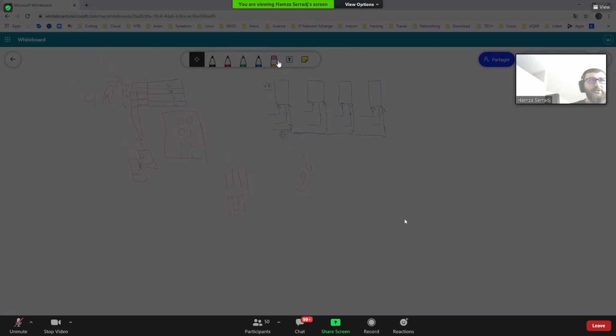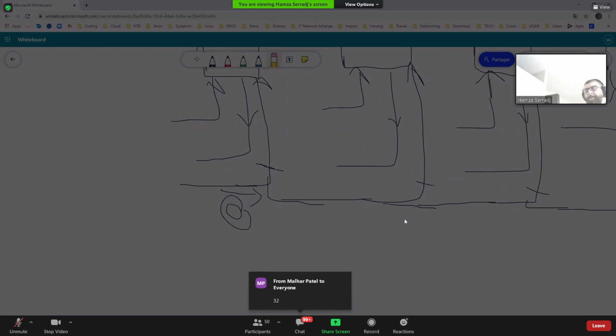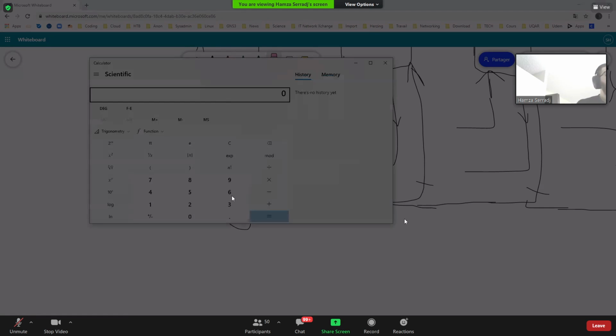I have 1024. With how many wires can I address this 1024? So what's gonna be the width of my address bus here? By 32? Well, let's take the calculator, right? What is the possibility with 32? So let's see it. 2 power 32.